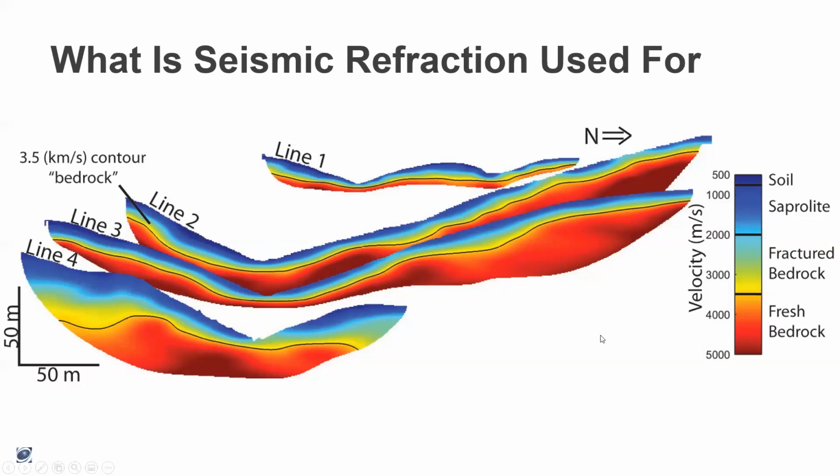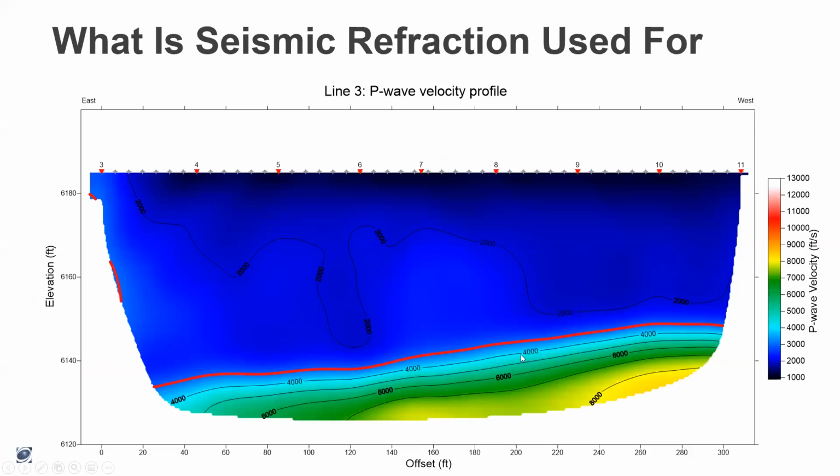Whether fresh bedrock from an academic perspective, which this was for, is the same thing as fresh bedrock from an engineering perspective, is a little up in the air. So you would need to work with your geophysicists to determine what your parameters for bedrock are, if you're doing a refraction survey for bedrock topography.